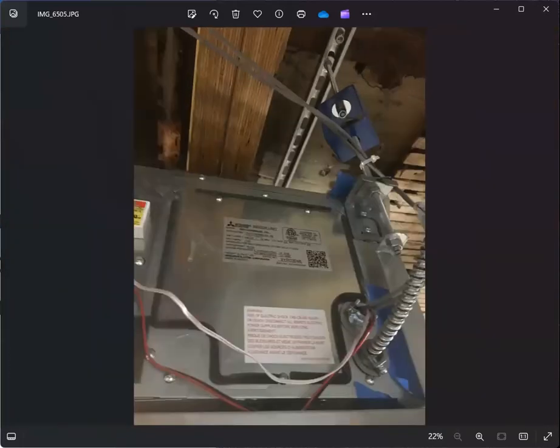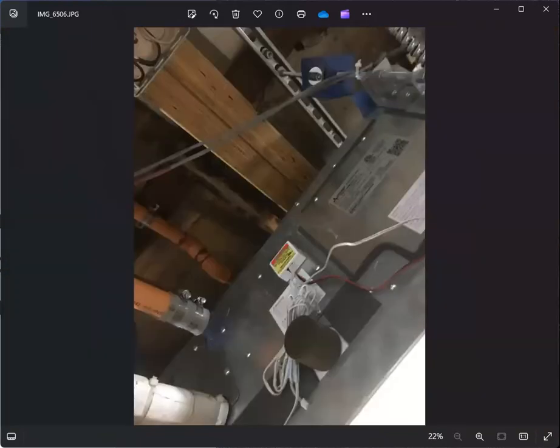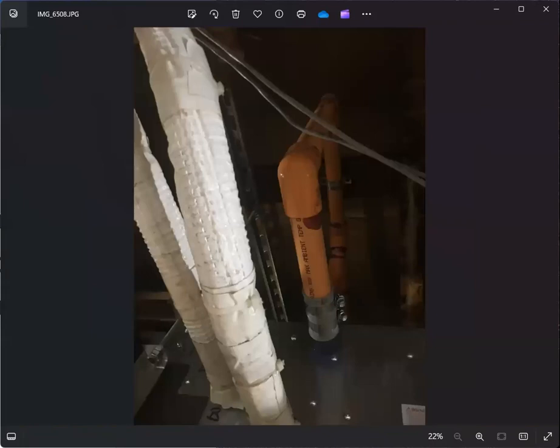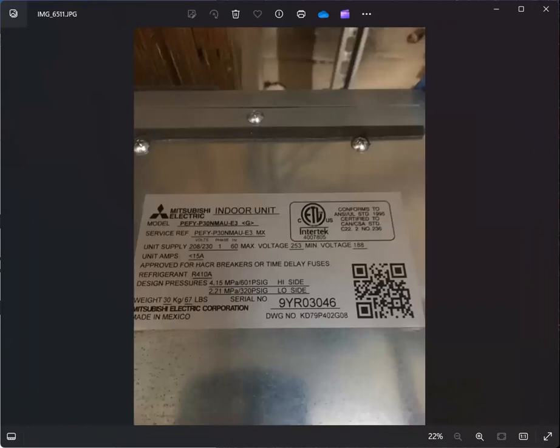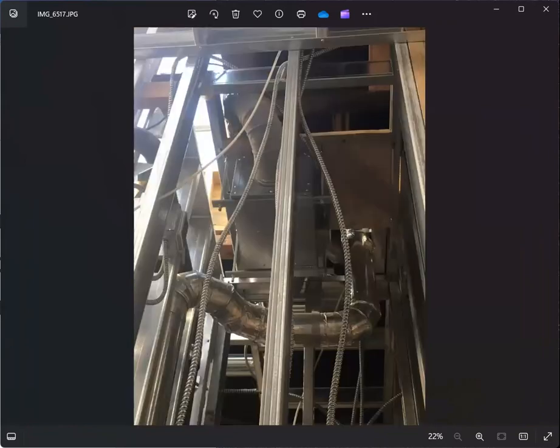If the unit that they're installing is too heavy or might produce excessive vibration, they need to have an absorption device like this. And this is the refrigerant line. This is the condensate line. You need to verify that all these pipes are installed properly and completely as per manufacturer installation or as per drawing requirement. This is another ductwork. If it's not for the toilet, it's for the dryer exhaust.